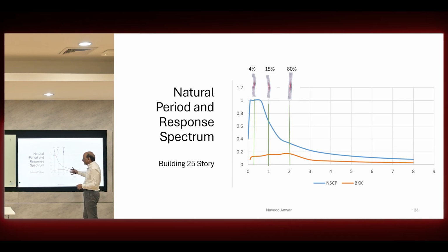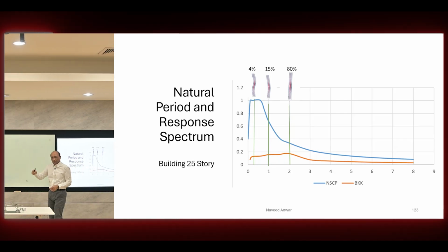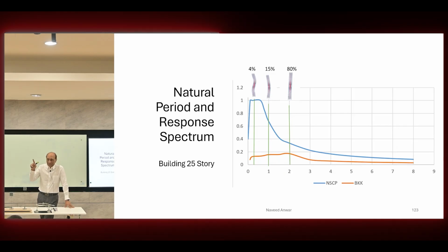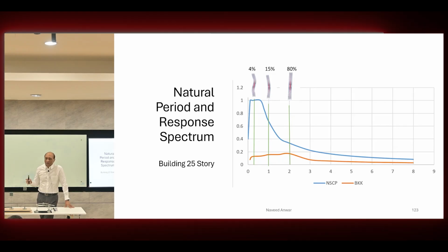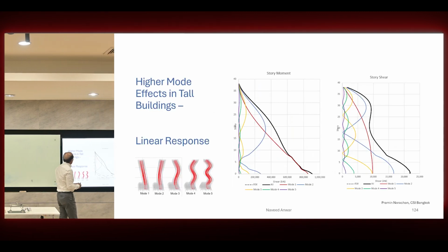Right? So this is very unique, but you can read everything from plotting the natural period on the response spectrum to understand what's going to happen, and the modal participation factor over there to understand the full picture. Okay, but response spectrum takes this into account for the total effect, but misses the local effects, especially when it comes to nonlinearity. And that's the point that I want to make. So please watch carefully the next one.